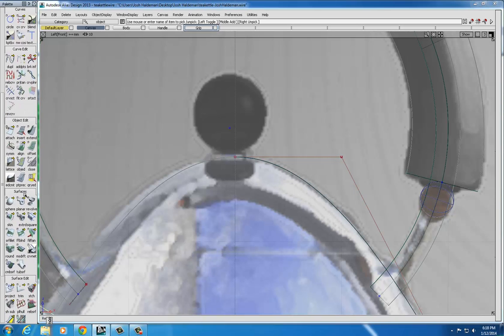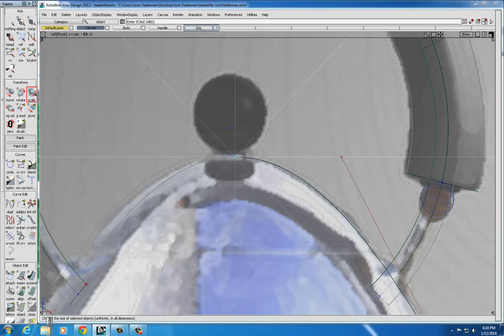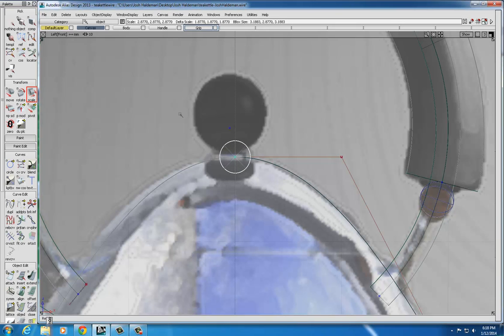But if you go down to the Surfaces menu, go to the primitive tools, click and hold with your left mouse button, and choose the cylinder tool. Turn on Curve Snap, and pick that initial curve, the first one that we created today, and drag it to the center at the top. Next, we'll scale that down, and I'm again going to scale it to size of 1, and I make it a little bigger than that. And I'm looking at my reference image to determine what the correct width should be. Like I said, it's a little offset, so it can be a little hard to tell, but we can get it close.